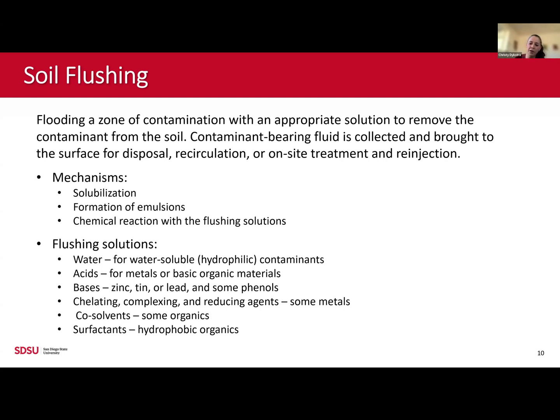We had a certain period where when the pH dropped, we started to see metals come out in the leachate, because the metals were becoming solubilized and being carried with the liquid to the bottom of the landfill. But then once we increased our pH, we didn't see those metals anymore because they reprecipitated back out and became trapped wherever they were at in the landfill.